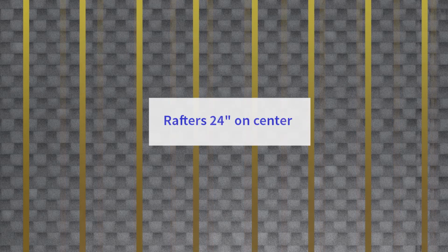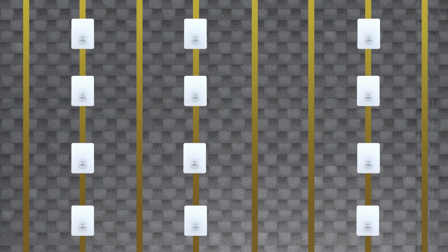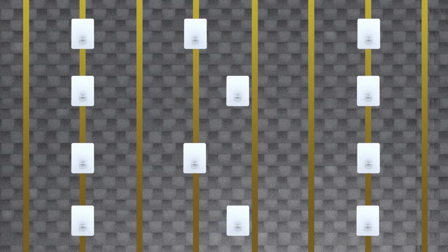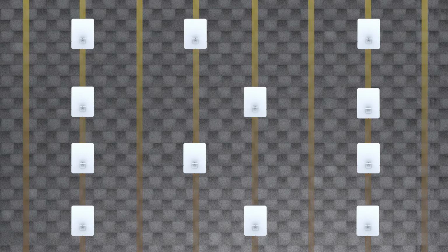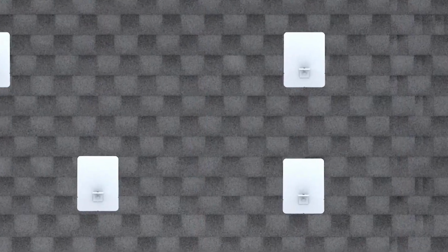Rafter locations and aesthetics will determine where you will fasten a mount to the rooftop. The roof attachments must be installed at defined distances based on the position of the array on the roof, module orientation, the spacing of the rafters, and module clamping zones. The allowable racking cantilever dimensions must not be exceeded.